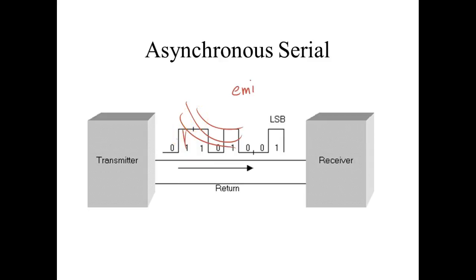So single-ended is limited in length. So our serial interfaces were really, really limited as to how far we could go. Single-ended interfaces, like the maximum for printer cables, were 15 feet. That was the maximum you're supposed to run. So they can guarantee maintaining ones and zeros over 15 feet. If you went beyond that, it was no longer guaranteed. Huh?